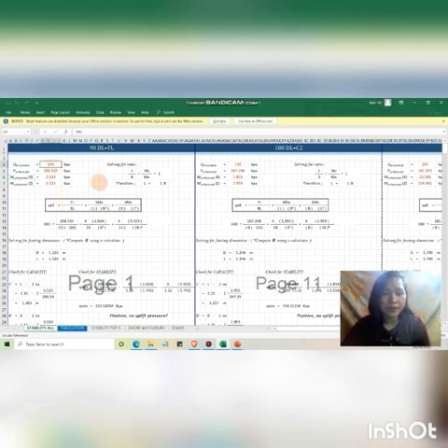For our Q allowable, we have here 190 kilonewton per meter squared. It is an assumed value. Next is the PY equal to 296.535, MX 2.024, and MY 5.523. We use the absolute values of these parameters. Solving for our ratio, we have L to B equal to 1 because our footing design is a square footing. So length and base are just equal.